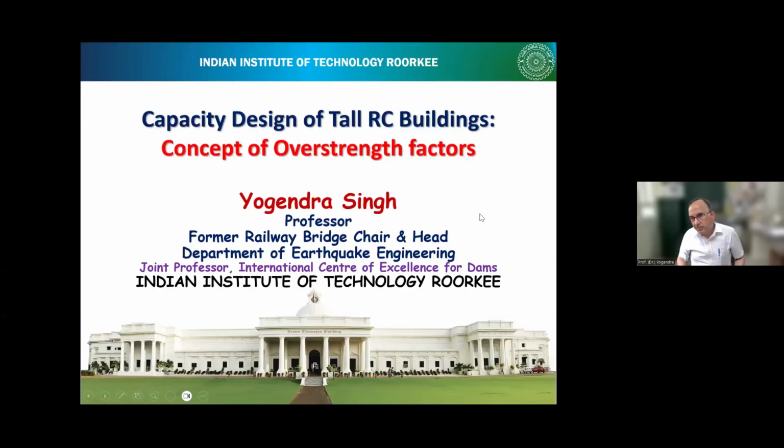Okay, so we are into our second talk now, and I have slightly focused this more on capacity design of tall buildings, because analysis and design of tall buildings is a much wide topic to cover in 1.5 hours. So I thought I will focus on this new concept which is coming in our revised code, that is overstrength factors. So we have to design with overstrength load combinations, and the basis for that is in capacity design.